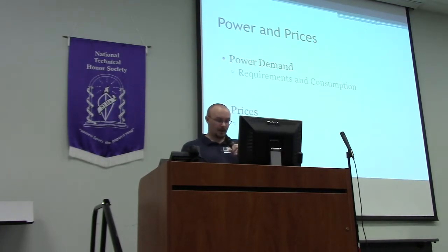The bottleneck is due to the PCI Express connection, which is limited to supplying 75 watts. Modern video cards with power consumption over 75 watts usually use a combination of 6-pin 75 watt or 8-pin 150 watt sockets that connect directly to the power supply.